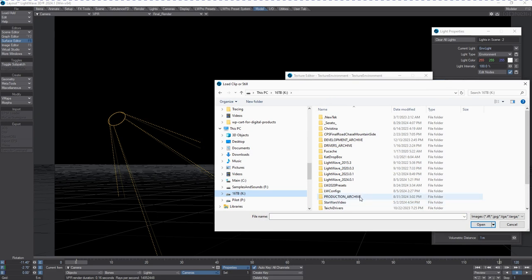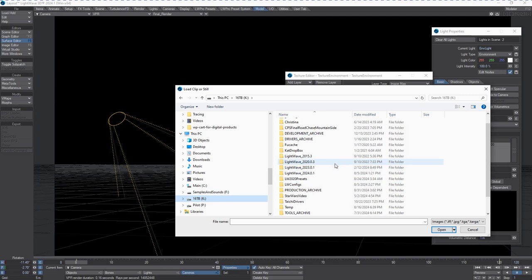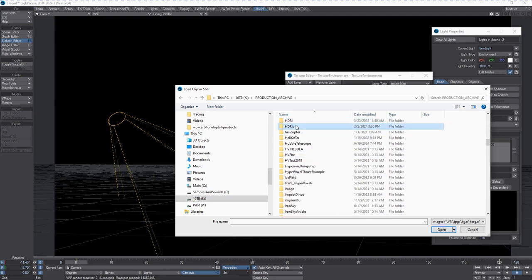Lightwave was able to do it as part of a radiosity solution starting in Lightwave 6.0, but there were a number of ways for us to fake doing that way back when, prior to that, for a number of years, by putting a spherical image on top of a sphere and then having the transparency set to about 50% and then shining lights through the actual surface and letting the light actually pass through the image and contribute the color from the image onto the objects in the scene.